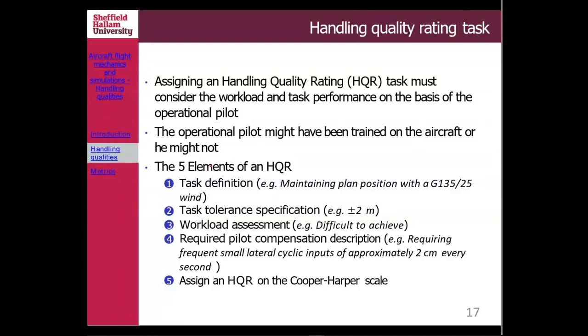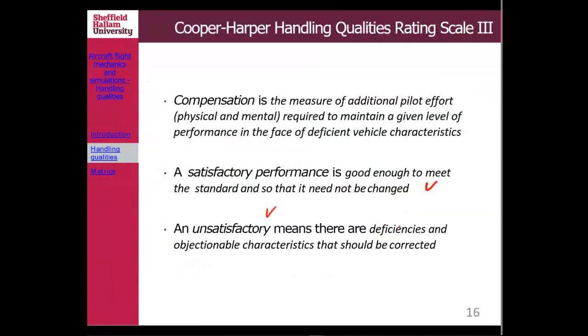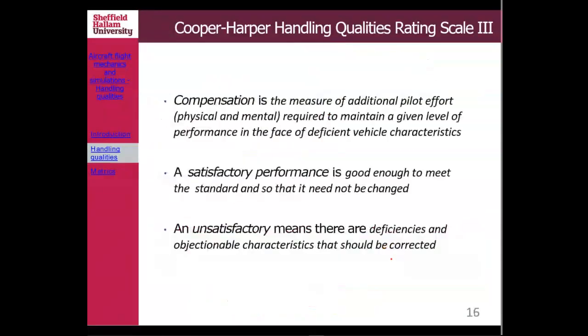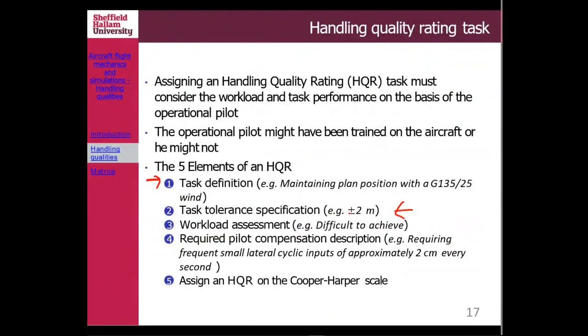Okay, but in this case, when you do the flight sim assignment, you don't need to worry about the task definition, because Johnny already mentioned that in the assignment brief: bank hold, pitch hold, altitude hold, for example. So the thing that you need to decide is, as I said, the task tolerance, right? When we talk about how you decide the band, for example the desirable and the adequate band, how much it is, then you need to be wise as an engineer. You need to define those task tolerances.